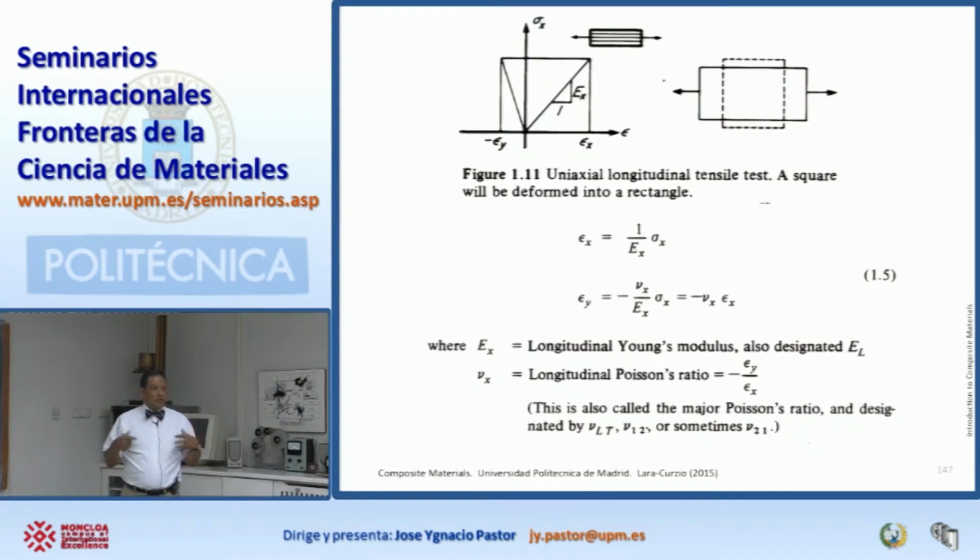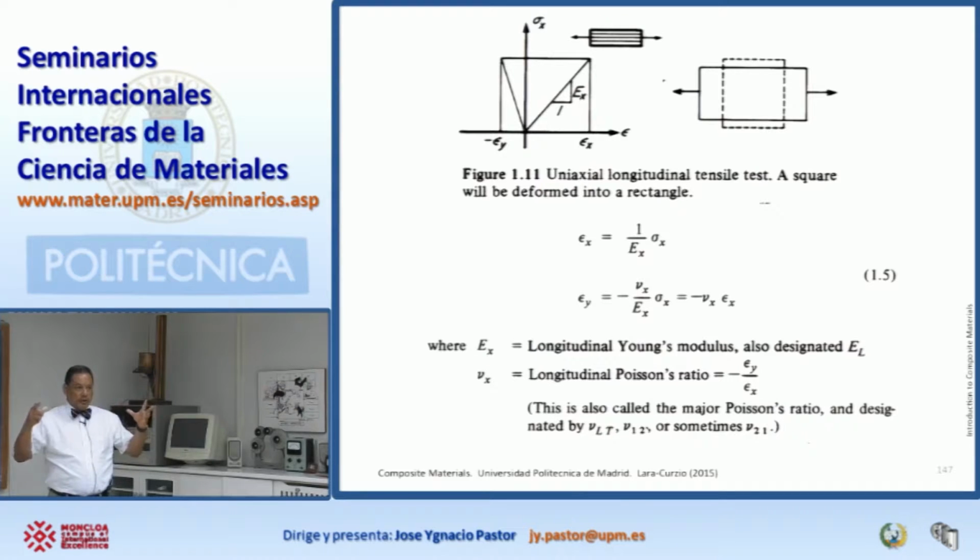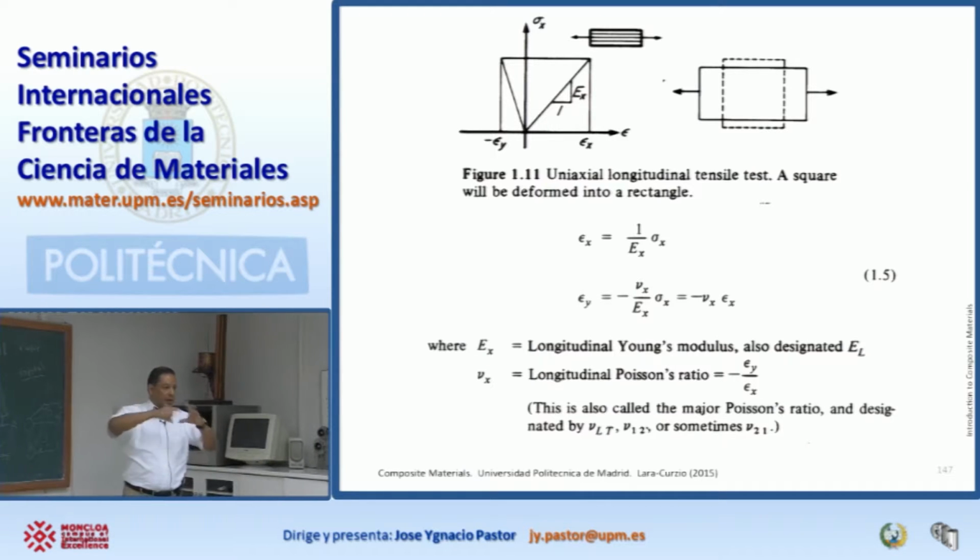So that's where finite element analysis comes into the picture. You have somebody with a workstation, and they say, OK, we have the fuselage. It is 30 feet in diameter. It's going to have internal pressurization. We're going to see some torsion if there is a storm, and there are stresses when the plane is going through a storm. We're going to have some bending. It can be combined bending and torsion. There's going to be some vibration. You put that into the workstation, and then you calculate the type of stresses.